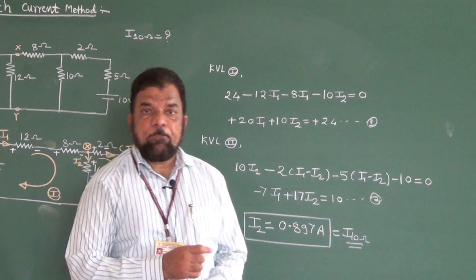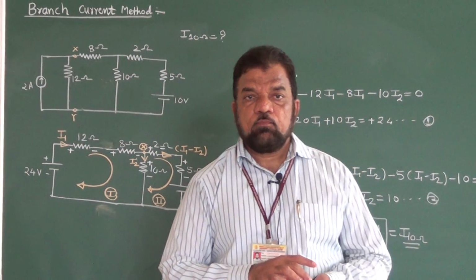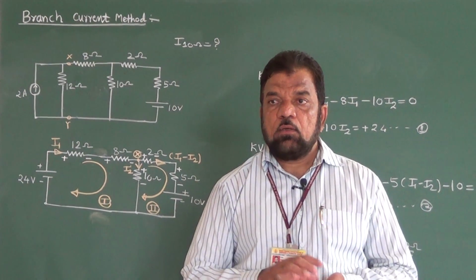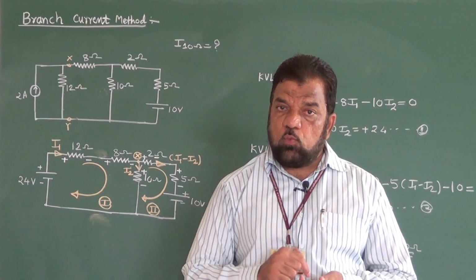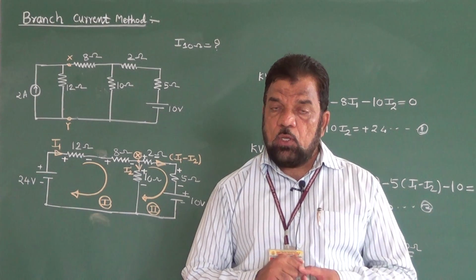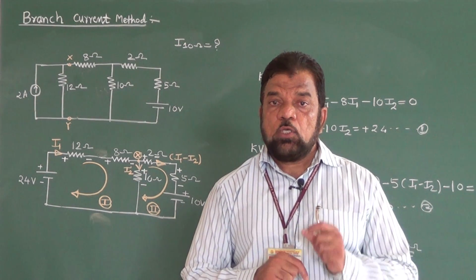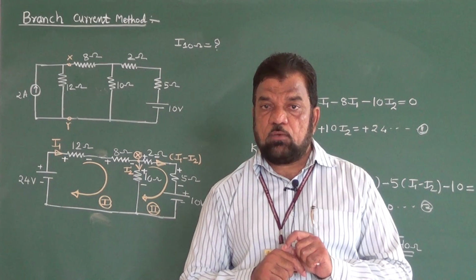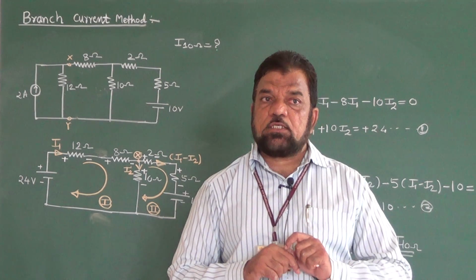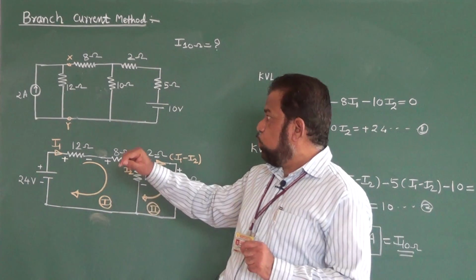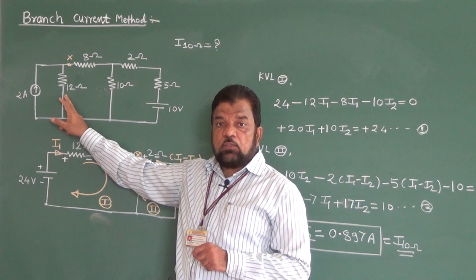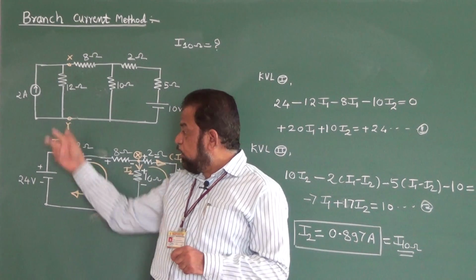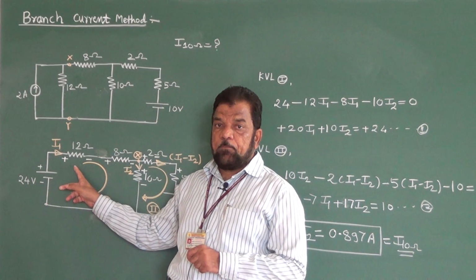So very quickly, if we recall the procedure of solving a particular circuit which includes current source in parallel with resistance, first make use of source transformation theorem. Now that theorem states us, whenever there is current source like this one in parallel with resistance, then we have to convert that into equivalent voltage source.